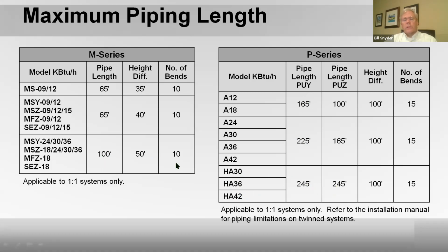And the number of bends, I don't typically consider a bend. If you take the refrigerant pipe and bend it, like this, I don't consider that an elbow. As long as it's a very, very long radius bend, it's fine. If you're going to braze in short or long radius elbows, never use short radius, but long radius elbows, then not only do we braze with nitrogen, but we would then start counting the elbows that you put in, the number of bends.